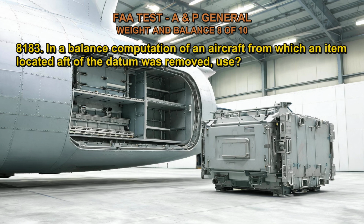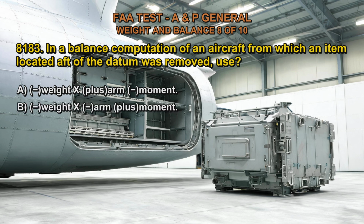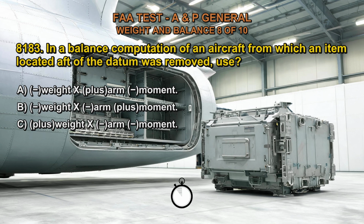Q8183. In a balance computation of an aircraft from which an item located aft of the datum was removed, use A. Minus weight times plus arm equals minus moment. B. Minus weight times minus arm equals plus moment. C. Plus weight times minus arm equals minus moment. The correct answer is A.